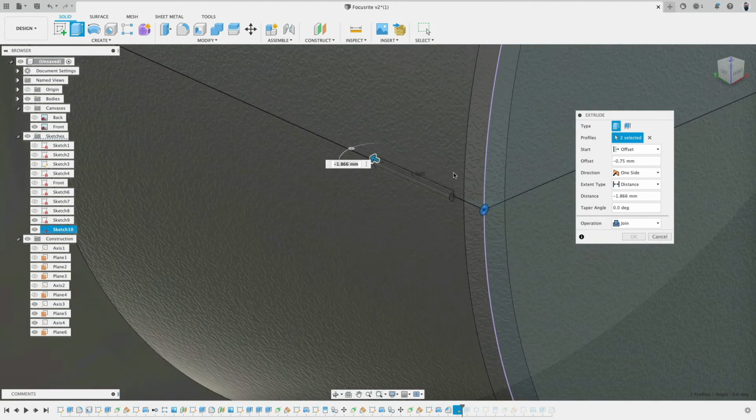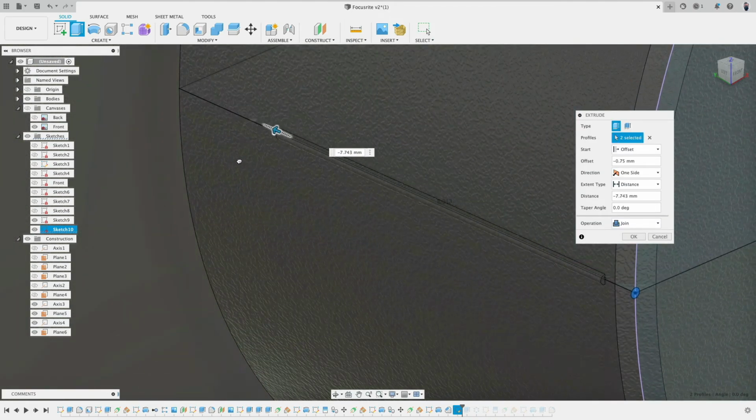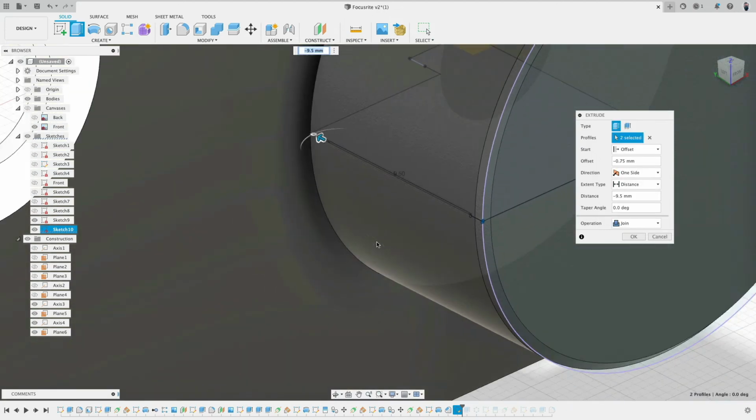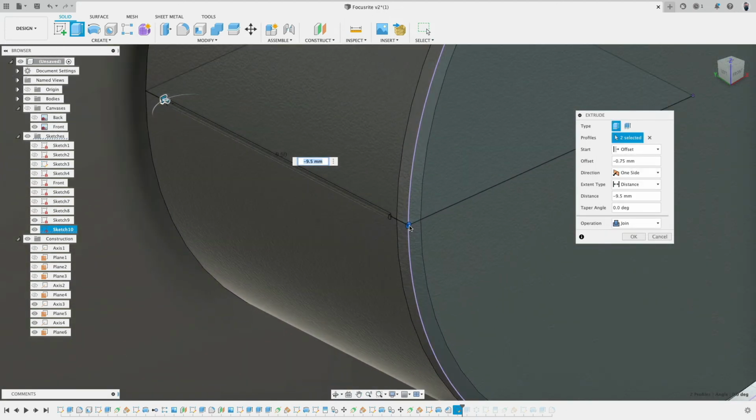Okay, but actually join the piece. Thank you. Then you can run down till there. So that looks like 10.5. Okay, and I would like 2 millimeters of a distance to the end. Or maybe just 1 millimeter there. Cool. So that's the way how you can do an extrusion of a profile and make it start somewhere and end somewhere else, than just at the beginning plane.